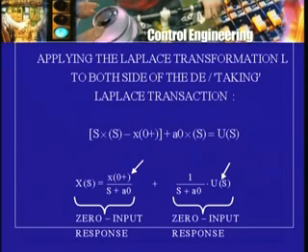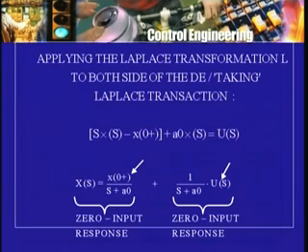Now if you wanted the solution of the differential equation, then of course it is necessary to know what u as a function of time is, to know what its Laplace transform u of s is, to be given also the initial value x0, and then do the Laplace inversion of the right hand side here. And we saw that this term corresponds to the 0 input response, and the second term corresponds to the 0 state response.